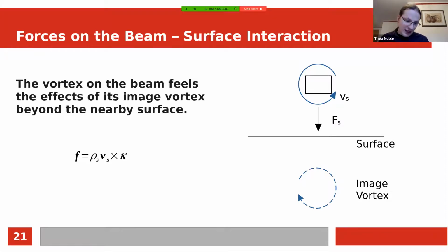In our own modeling, we've been able to get about a 1 gigahertz jump. Our own model is quite naive. We don't include many of the intricacies of the system. We assume the nanobeam has uniform density, which it does not. It's a composite beam, aluminium on silicon nitride, and we also assume the nanobeam is very nicely smooth. It's almost definitely not. It's going to have rough edges, etc. There are many intricacies we don't factor in. So we're quite happy to be on the same order of magnitude in our calculations, but this is something further work could go into.